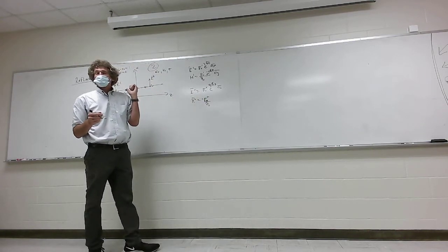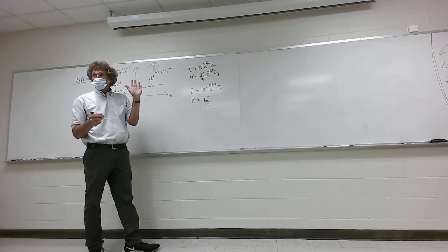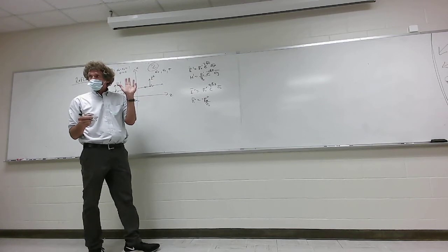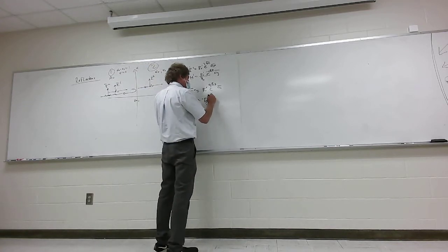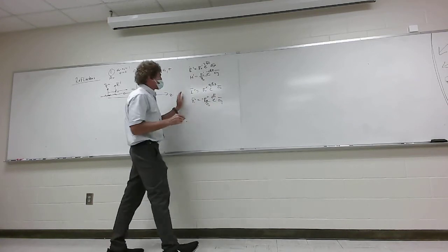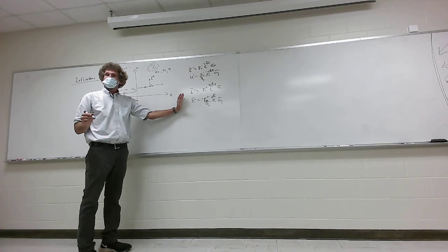Remember, the ratio of E naught over H naught for the positive going wave was eta naught, and for the negative going wave it had a negative. Do y'all remember that or not? This will have a negative sign, and it will be e to the j beta 1 z, ay. So that's the incident, that's the reflected field. Follow me? This is consistent with what he's doing.